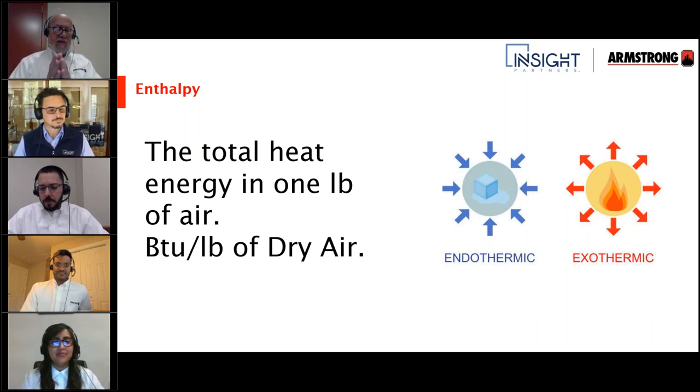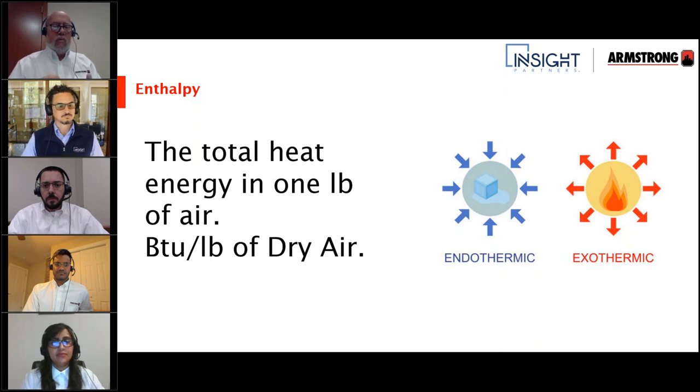Well, understand that when we look at temperature and sensible heat, that's what I can feel. I can measure it, I can feel it. If I grab something that's hot, I know it's hot. Enthalpy in humidity is the energy you can't feel. We know it's there, and we can feel it in the sense that you walk outside and it's hot and muggy, and you feel how oppressive the air is. That's the only way you can really feel enthalpy. Enthalpy is really the mathematical calculation of how much energy there is in that air that we've got to get rid of and that we've got to deal with.